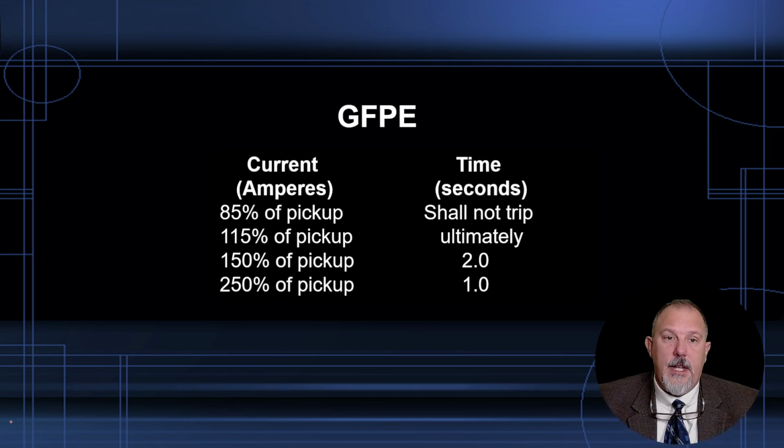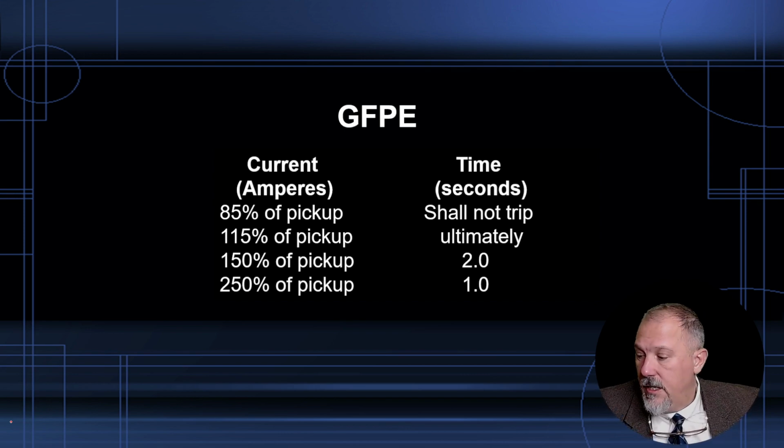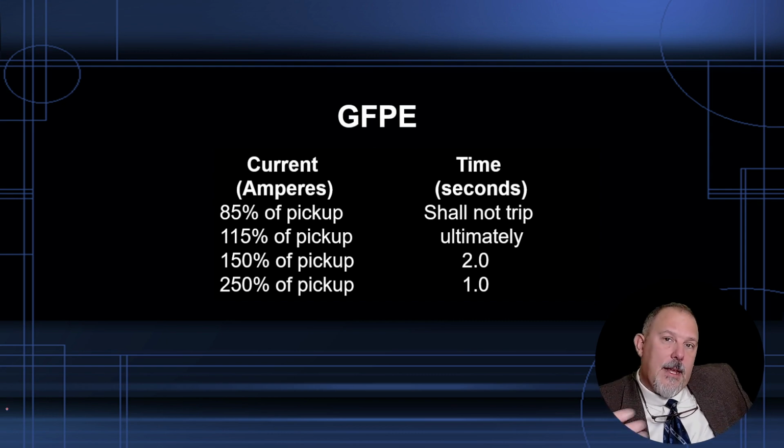So typically, these ground fault protection devices, outside of, say, your 30 milliamp, there's nowhere in the code that tells you 30 milliamps. But the industry is pretty much standard on around 30 milliamps. So that is the pickup point. Remember, it's a pickup point, not a limitation.